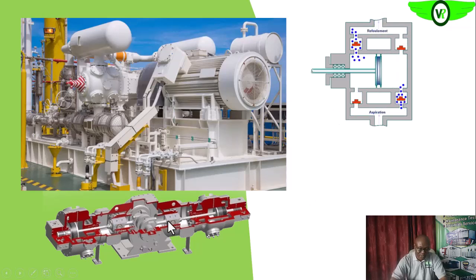So this is the type we have here. You see that we have double acting reciprocating compressors on both ends of this, and this is where the driver is attached. That is the crankshaft, and this is the connecting rod to the piston. This is one chamber and this is the other chamber. It compresses, discharges, and then once it's returning, it compresses and discharges.